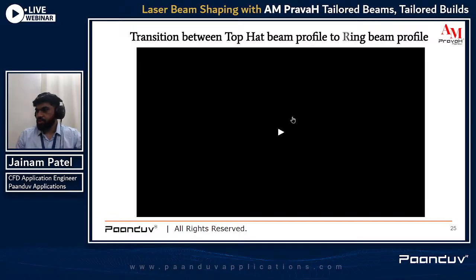Is it limited to AM only, or can it be used for any other laser material processing also? Yes, it can be used for any laser assisted AM process. So the user can create n number of different shape profiles in the LPBF process. Yes, we can simulate any laser shapes with this software. But the user just needs to enter the radius points and intensity points for that.